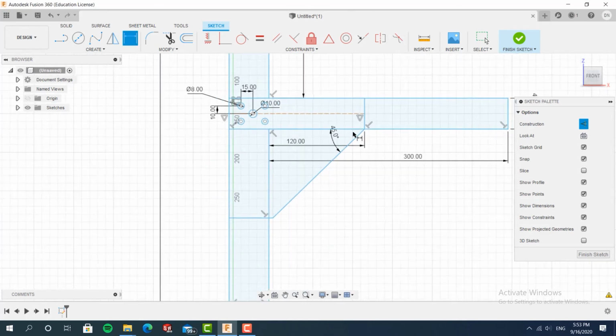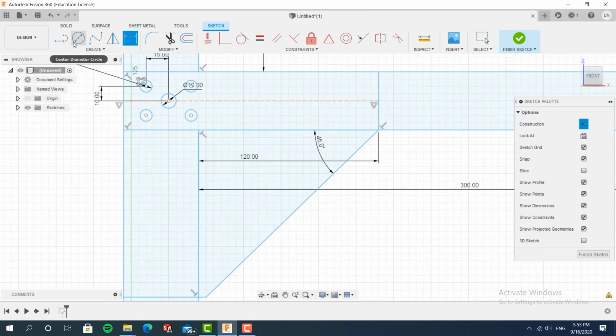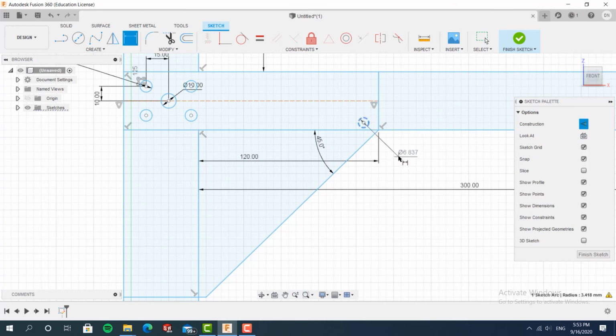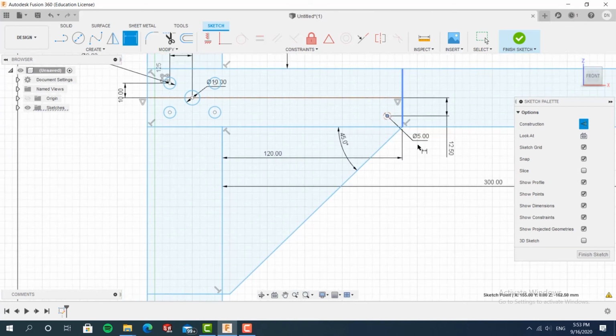Generally, everything will have a bit of backlash, and the further away it is from the support, the more backlash it will have, which will be a really bad thing because it will mess up your calculation a whole lot. So you need to support all of these different parts to minimize backlash, to minimize damage to your robot. I will now name some things that are normally used for support. There are going to be guides, flanges, and gussets.